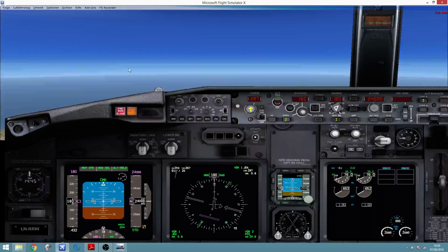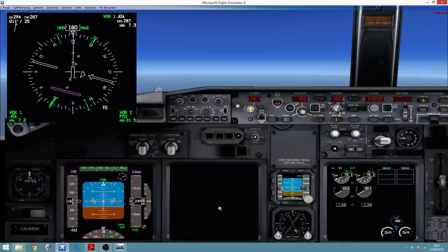But please be aware that this is just providing us indications of where these stations are with respect to where we are now. This is by no means influencing or modifying the trajectory of our aircraft. We can just modify the trajectory of our aircraft by selecting the heading here, the lateral trajectory of the aircraft. So if I wanted to turn left to go towards Papa Oscar Sierra, which would mean a track of about 030 degrees, as this thick green arrow is showing.